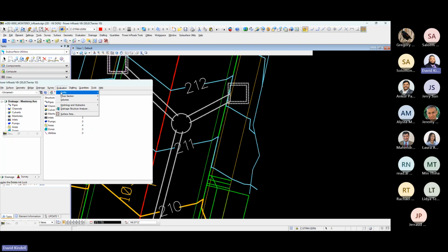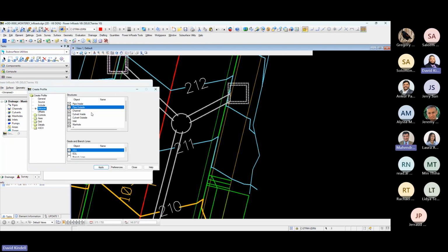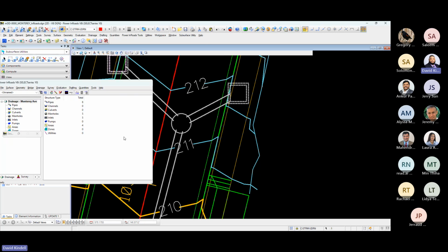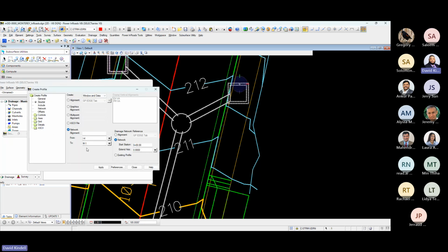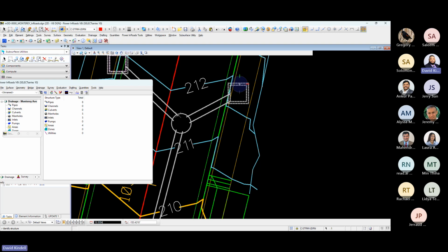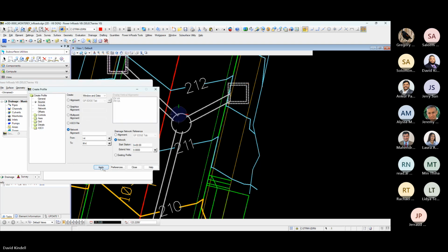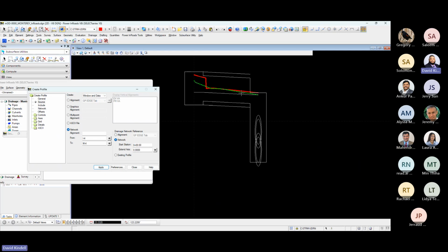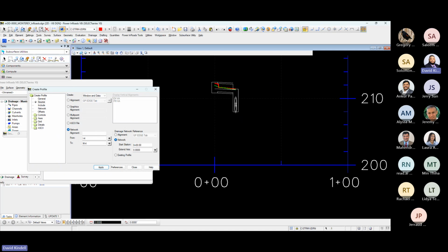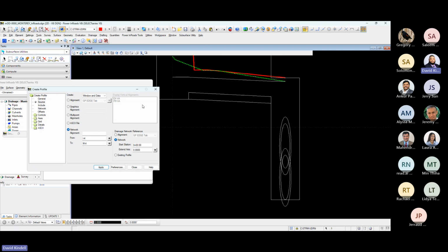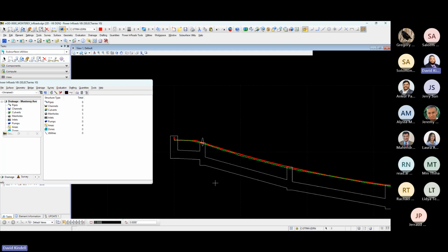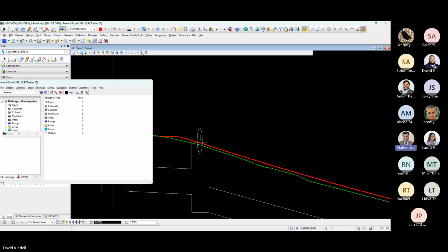You can create another profile, okay? Create a profile. Choose a different source. Go from I3 to manhole two and click apply. Okay. Now when you move this thing down, this pipe is showing this pipe here.